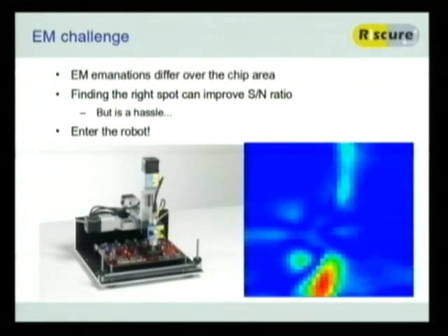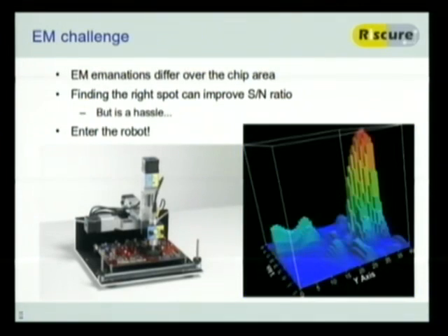You typically are looking for certain frequency components. For instance, on a smart card there's usually the main CPU, but there's also crypto accelerators. And these sometimes run at different clock frequencies than the main CPU. If you go into spectral filtering, you can focus on those particular frequencies that you presume are the ones from the crypto clock, and that way you get a much better signal-to-noise ratio. And that sort of outputs these kind of things. And if you really want to impress your girlfriend, then you print them in 3D.